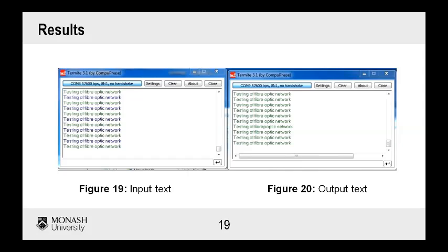If you look closely on the right-hand side, there has been a bit error, which has caused a space to turn into a P. We did not do any form of bit error calculations because we also noticed that bit errors would occur when the two PSoC chips are connected just by a wire. This made it impossible to see whether the bit errors were the result of the two circuits that we made.